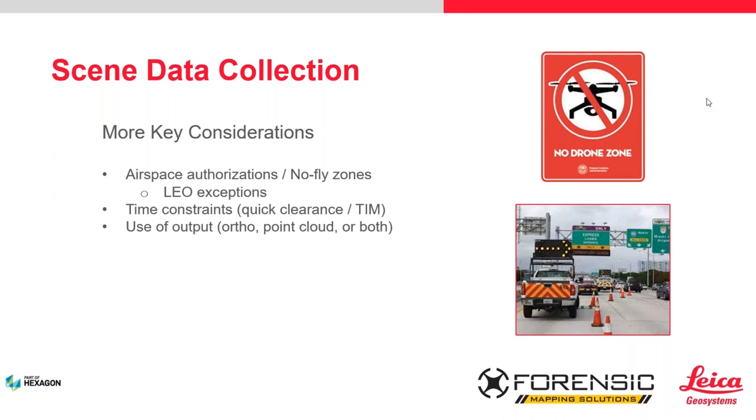And then finally, as far as airspace, you have the issue with the drones themselves. DJI, which is what most people fly, has no-fly zones, or geofence no-fly zones. That has nothing to do with the FAA. It has to do with the drone itself, where they're saying that it's not a good place to be flying. It's near an airport, it's in controlled airspace, and you won't even be able to power your drone up. There's also a way for public safety to deal with that, and it's called the Qualified Entity Program, and we'll give you the information on that too. If you're flying drones for this type of work and you have not got your drone unlocked by DJI, put it on your list, because if you wait till you need it, you're going to be not too happy.